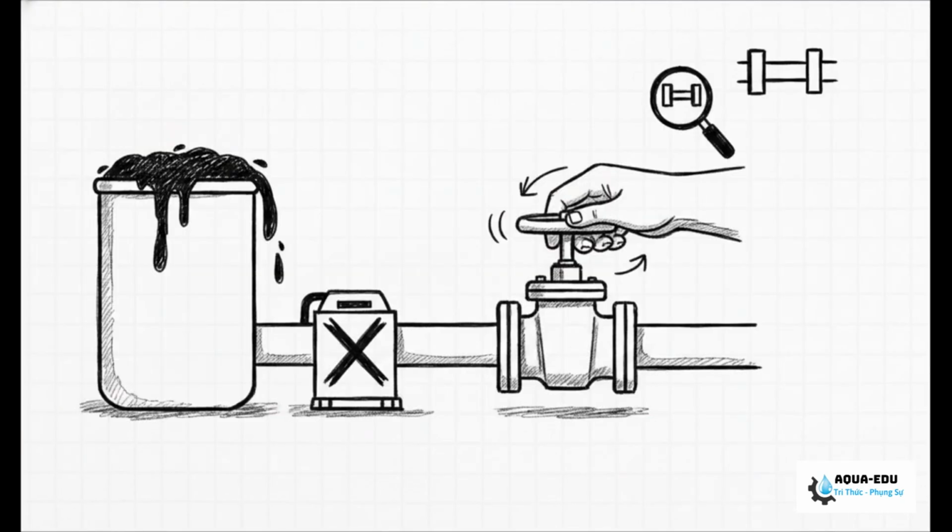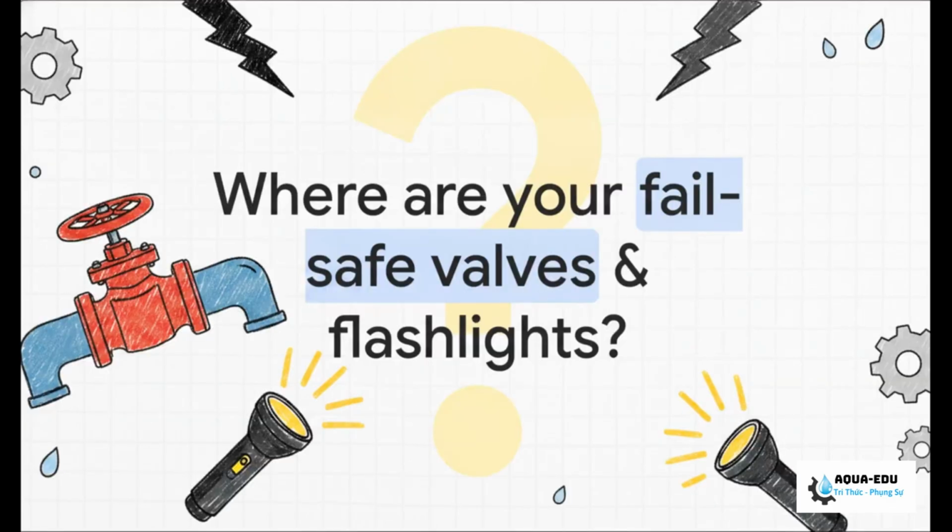Let me reiterate how absolutely critical it is to know your valves, brothers. If wastewater just keeps flowing into the plant by gravity, but your pumps are completely dead, you are marching straight toward a catastrophic biological spill. You have to manually verify if your critical valves failed open or failed closed. And if necessary, you must manually override and close those inlet valves to isolate the system and buy yourself some much-needed time. We've covered a whole lot of ground today, but it really all boils down to readiness.